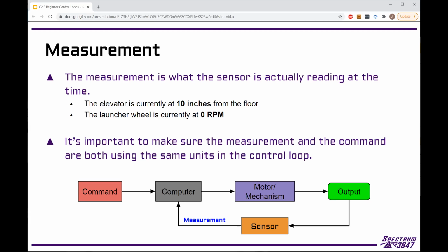Then there's other types of different units and just choosing different things. So you could, in theory, be in revolutions per second if you wanted. There's things that use like encoder ticks per 10th of second or something. Like, there's all sorts of units you could be in. So you always want to make sure you're matching those up and getting them right before you're doing the math. And it's just something to think about. Most of the time it's done for us, but on occasion, if something's just not working at all, that may be a place to look to figure out why it's not working.